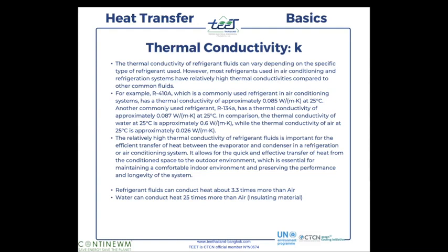And they propose it to some company, but first, not all air conditioning, you cannot just remove the old refrigerant and put the new one, because the compressor has some setup. The way the compressor and the expansion valve in the air conditioning function are designed for a specific refrigerant in general. It's like if your car uses gasoline, you cannot put diesel inside because you will not go very far, okay? It's exactly the same principle. So not all air conditioning, you can change the refrigerant fluid that is there.